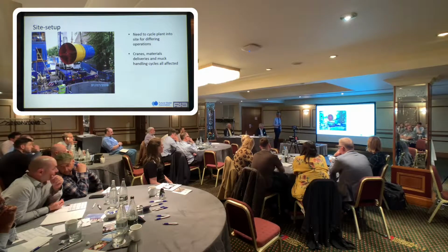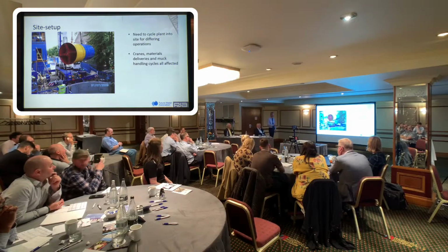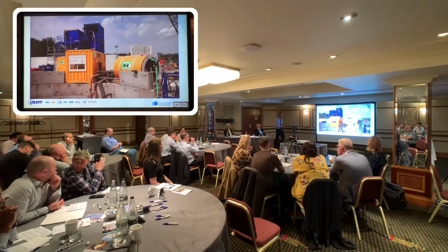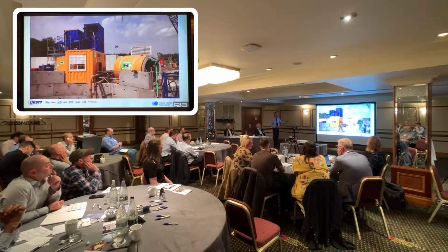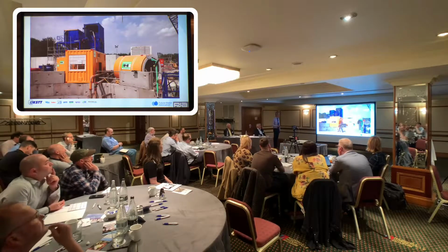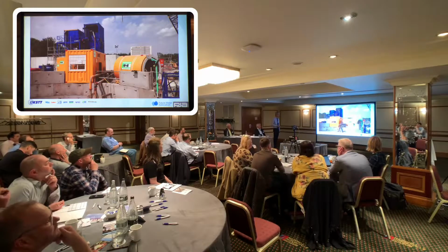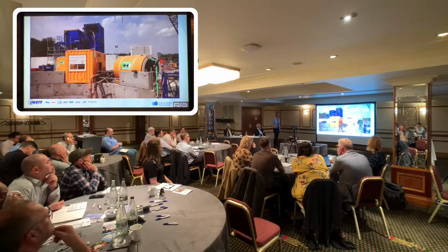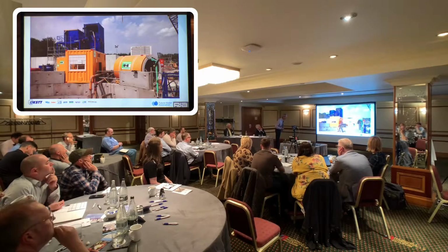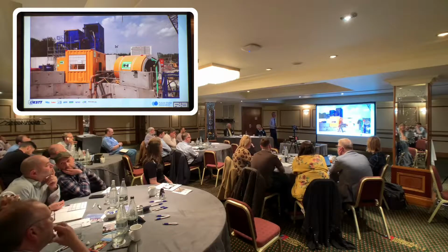And that's an Iseki microtunnel machine. Didn't recognise it, sorry. That's more like it. And there's an air connect. So again, it's another view of another site, control cabin over the site. These are your slurry lines going down from the separation plant. There's the advertising on the side. I think that's the back. That's the pump can, the middle can. And this is a lubrication mixing plant.